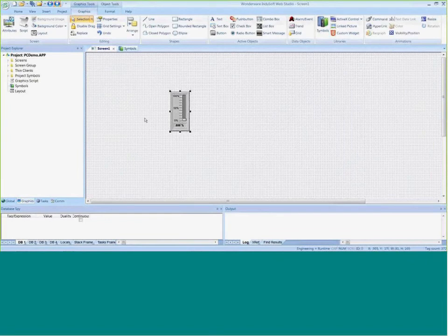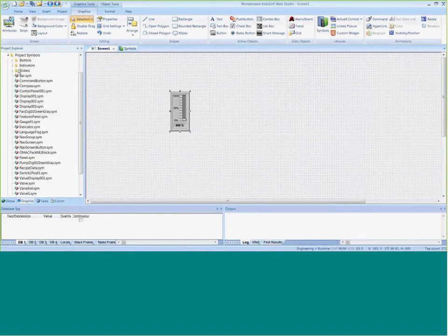As I mentioned, this slider, I took a copy out of the symbol library and put it into my project. So now it lives here under the sliders in my project. And if I make a change to this, then it will be linked to all of those others throughout my entire project. That's why we call it the linked symbol, because all the symbols that refer back to that one common design are linked to it. The third piece is what we call custom properties.